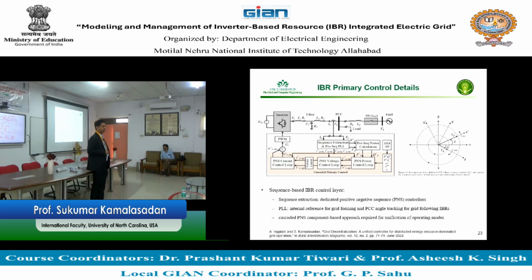The good news of this is, and now we don't have time to talk about that, but if you are having abnormal operation on the grid, which is faults, for example, one of the good news about a synchronous generator is what we call fault contribution. Have you heard of the word fault contribution? If you have a fault, what will the fault do? If you have a short circuit, if you have a line falling on the tree, what happens? It is going to draw current, okay, and we call it fault current.